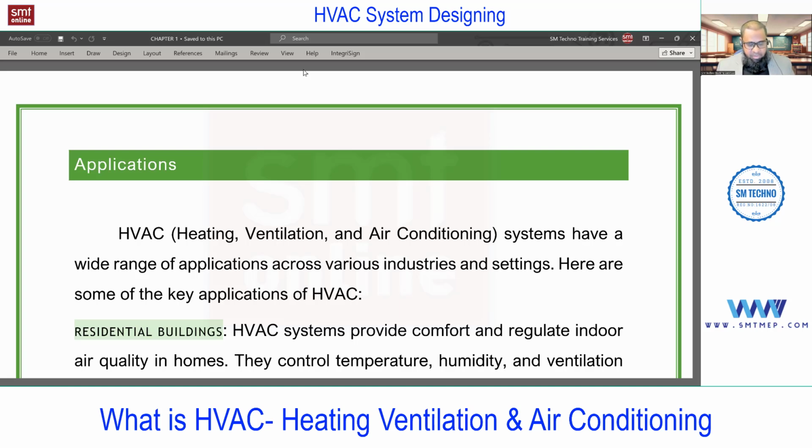When you provide the fresh air, definitely there should be some provision for exhaust also, or else the room will be continuously getting air from outside, and there is no exhaust. After some time, the movement of air decreases, and the pressure inside the room increases. That will affect the back pressure of the equipments. So definitely what you're thinking is required, and for that we have provision also.